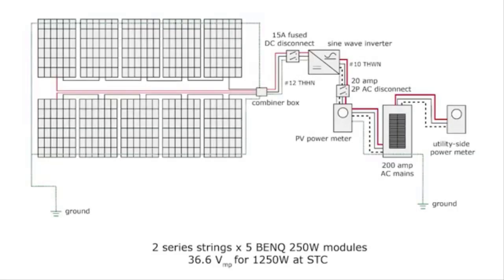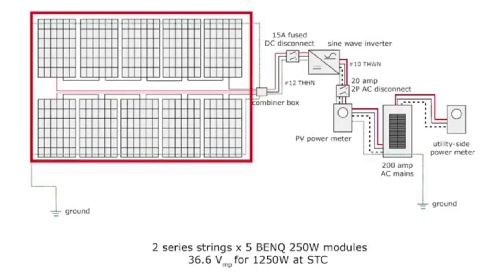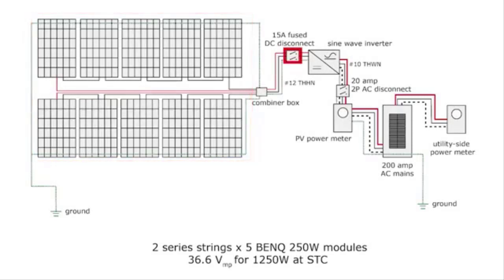Once all the electrical components are considered, a system diagram can be designed by a solar designer or an electrician. This is a 3-line diagram that shows where photovoltaic modules are wired to a disconnect, the disconnect to an inverter, and the inverter wired into another AC disconnect, and then wired to the main breaker, which then connects to the rest of the building components as well as the utility.